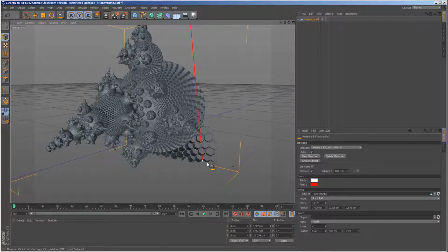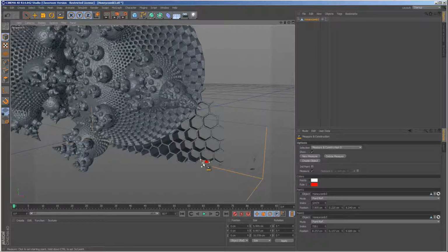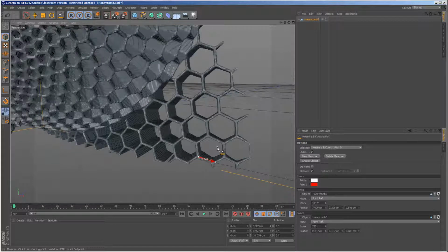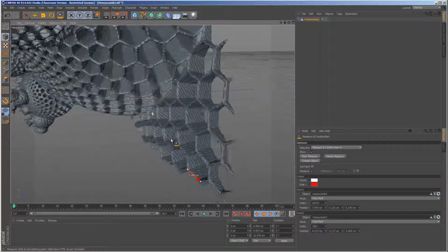Now when I do this, if I click once, it brings one dot, and if I hold the Shift key down and click again, it will let me make a measurement. Now, when I do this in the perspective window, it doesn't really work, because if I rotate this drawing around, you'll see that, oh, I guess it did in this case.